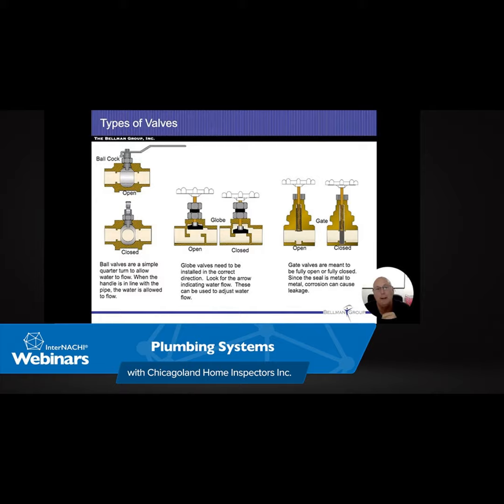So, dip tube we talked about brings the water down to the bottom. If it breaks, then we end up getting short cycling on everything. Anode rod, we kind of chatted on that as well. That's designed to be eaten away before the water heater gets eaten away.